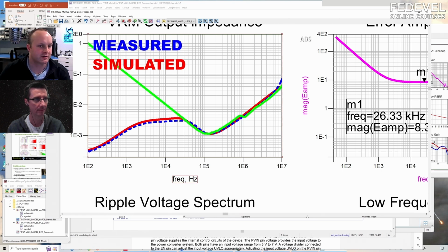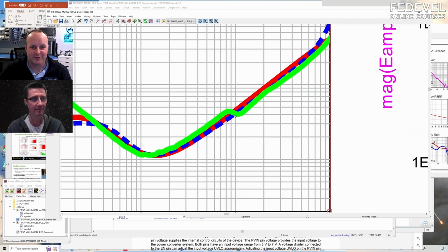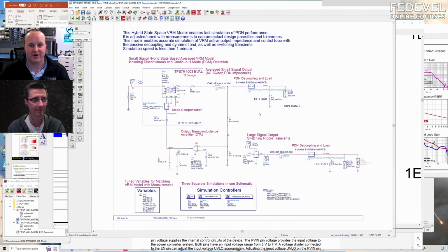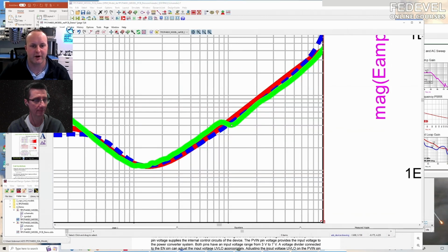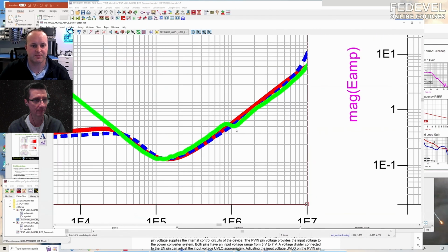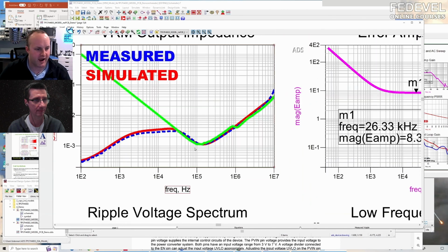And what I measured, I actually measured a different board when I made this measurement. So they're the same, but it didn't have that cap. That's what I'm gonna show you installed, so a slightly different configuration. So when I found this later, I made a very good example. But you can see right there, there's that little blip that I was just pointing at, right? That's part of our problem. So let's go and figure out, well, how do we figure this out? Well, we showed that there's a 1 megahertz dip there in our impedance, and that's probably a correlating factor.